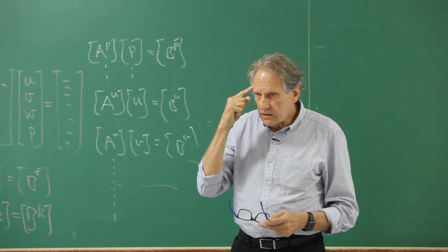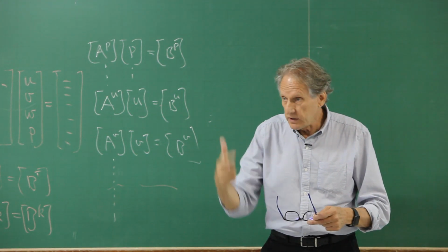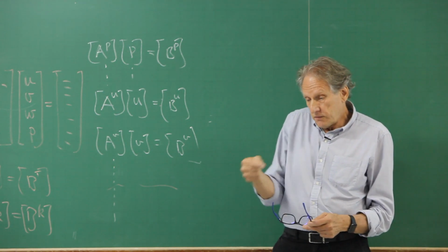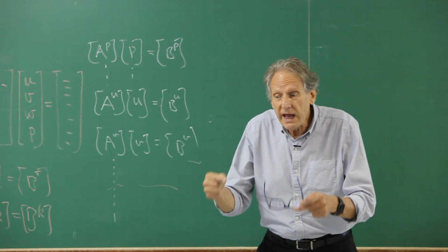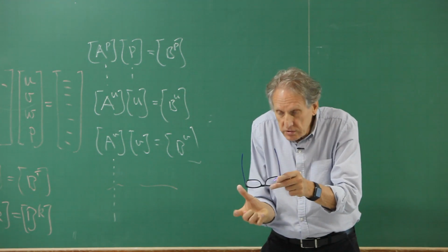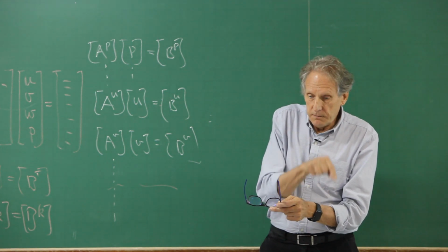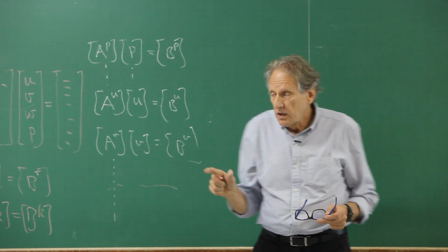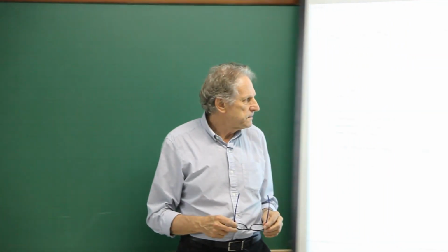Don't confuse same time here with the transient. The solution is not the same at the same moment in the algorithm. And then one, then the other one, using information of the other one, which is this nonlinearity coupling involved. And when it's simultaneous, the variables are being solved simultaneously, all together. The only thing which remains is the necessity for iterations because of nonlinearity, but the coupling is considered. Then I prefer to say simultaneous than coupled, but it's synonymous in the literature.